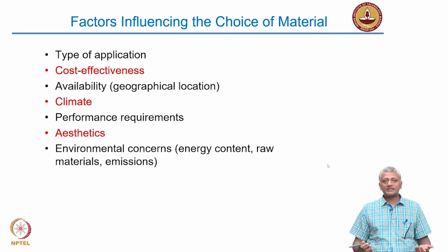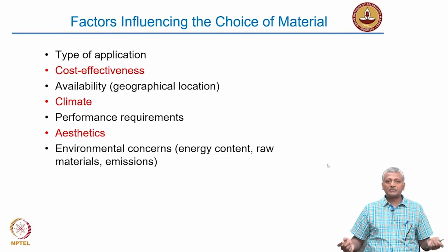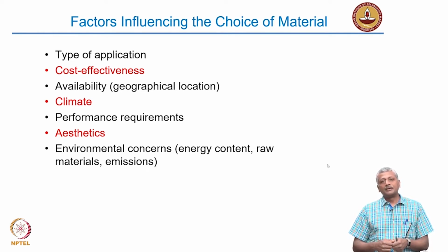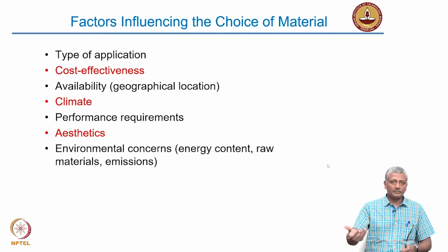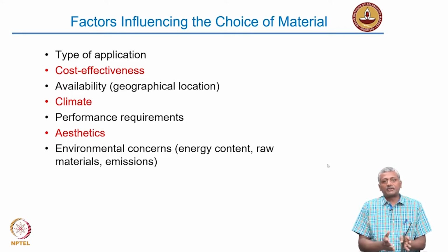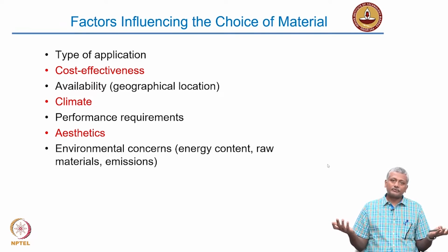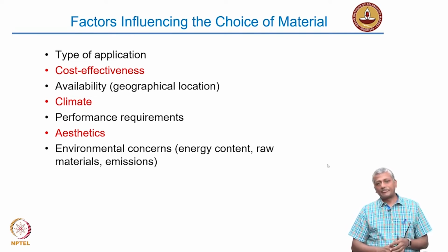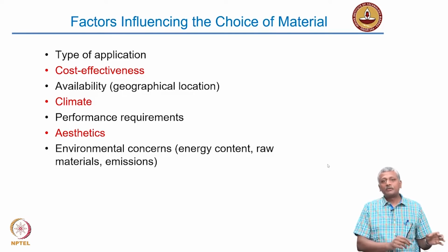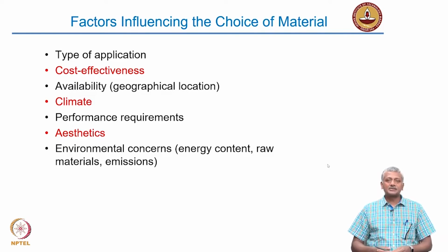So, it can actually function for extremely long period of time, but however, in modern structures, we employ concrete in connection with steel reinforcement. And steel obviously has a tendency to corrode. You can't stop that. It will corrode eventually. Okay? So, you can only design a structure for as long as it takes for the steel to corrode. If you design a structure with plain concrete, it may last for a very long time, just like your stone and lime did. Okay? So, there is no problem with that. However, when you start using steel, the service life of the structure is shortened because of the time to corrosion of the steel.